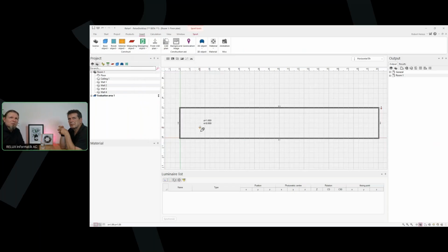has changed. So this emergency route has changed in concept from the 2019 version of 1838 to the 24th version. So the way to create an escape route is still the same. We do not touch the way of creating an escape route. Of course, with the new standard, you do not need to have this middle line. So we are no longer estimating and calculating. We calculate, but we do not need, in relation to the standards, to have values on the middle line. So we do not need to check and compare the middle line to the standards.